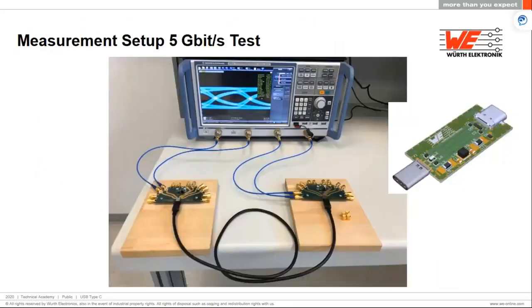Okay. Now here we have created a dongle for 5 to 10 gigabits per second. We show here that it's critical to have filter components and protection components such as common mode chokes on this side, ESD protection on this side, as well as some filter components such as inductors and ferrite beads for our power path.